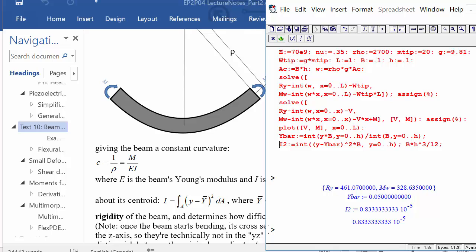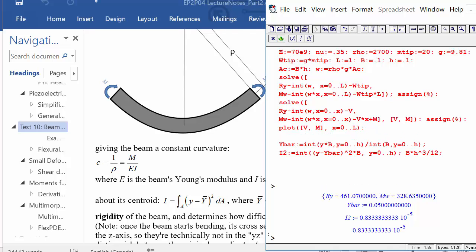So really, to make this as general as possible and account for a stiffness that can change with position in the vertical direction, we should end up multiplying this by the stiffness in the extending direction. So what I mean is account for the stiffness in the lengthening direction, because that's the kind of deformation that we've got. As we bend this, it's compressing in the length direction and extending in the length direction. So that's the x direction I'm talking about here. But if that stiffness in the x direction changes in the y direction, we should really put this into the calculation of y bar here.